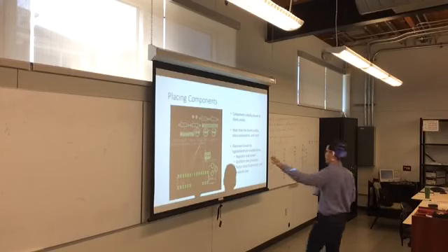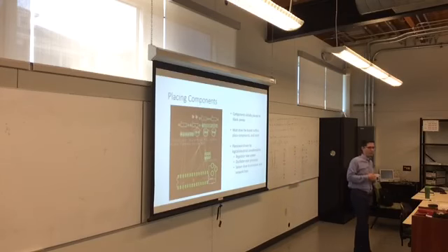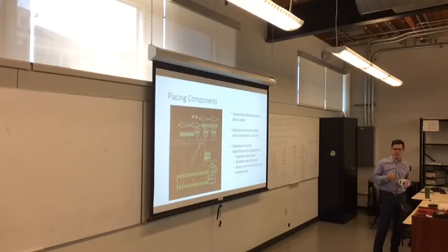If you're building a little microprocessor and it's operating at 5, 10 hertz, I wouldn't really worry about it, but once you start to get up into the gigahertz range, or once you do anything with the radio, now you have an analog problem. So if you've got a little Bluetooth built-in board, like Schmidt has back there, the antenna has to be of a certain shape for it to be a receiver on the board.